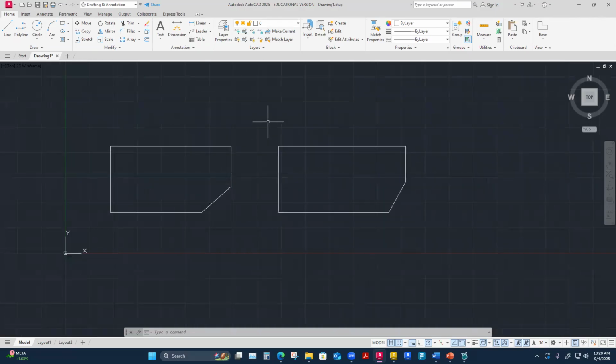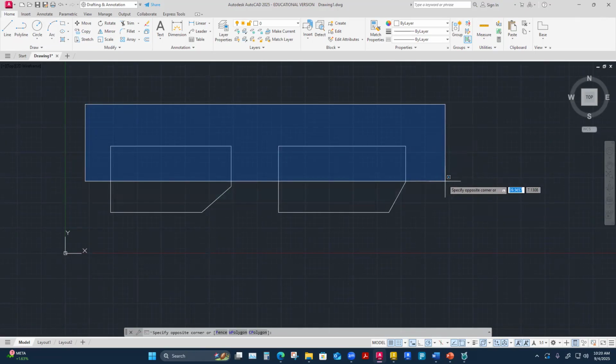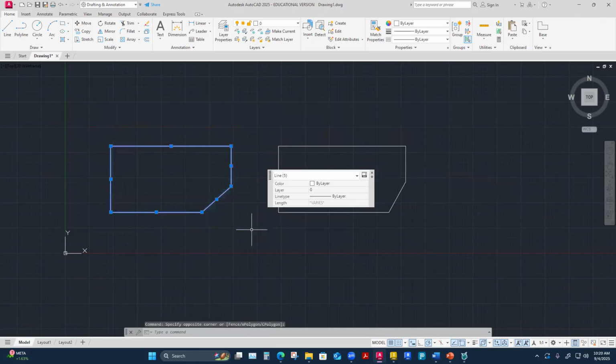How you erase, I'll do that really quick, you have a couple options. I'm not in a command at all, but if I click from left to right, it opens up this blue window. It's like a fencing system. If it's a blue shade, in order for it to do any deleting, it has to encompass the entire thing that you've drawn. You can see that nothing is highlighting here when I'm over it. But if I come over the whole thing, I can actually choose the whole thing.